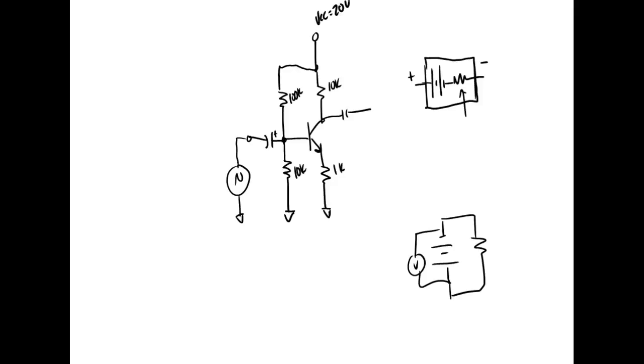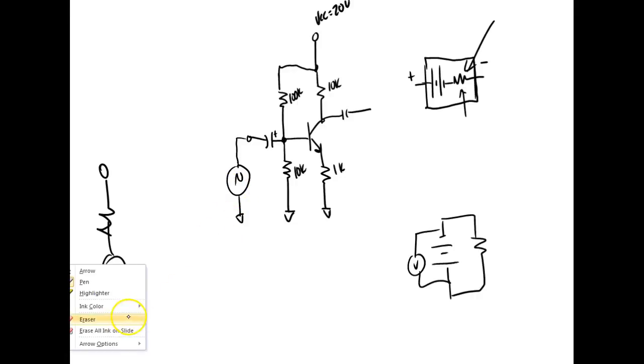But when I hook up a signal source, it will always have that resistor right there. We're not talking about a power source. Signal sources are not regulated. If I tried to regulate volume, then I wouldn't get any sound, right? You understand that? So every signal source has a resistor. So that means I come over here and I draw that little AC thing, then what I need to do on every one of these is put a resistor in series with it.